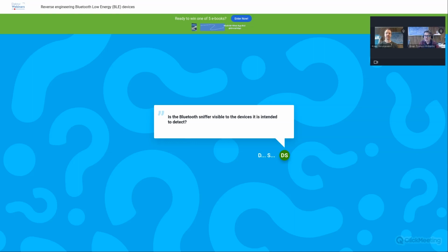Great. Another good question. Isn't there any encryption over BLE peer-to-peer communication sent over the air? Yes, I glossed over this detail because there are various types of security. There are different levels of security in Bluetooth defined. You can have no encryption, no authentication. You have encryption but no authentication. You have encryption and authentication. There are different types of how to bond with another device, how to pair with a device, how to set up this encryption.